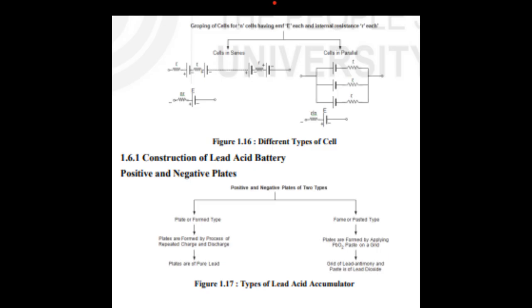1.4.2 Resistance of resistors in parallel. Resistors are said to be connected in parallel when the same voltage appears across each component with different current flows through each resistor. The total current flow into and out of the parallel combination is the sum of all the individual resistor currents, as shown in figure 1.6. Figure 1.6, Parallel resistance. Look at the screen. Two resistors connected in parallel may be used as a current divider. The voltage V appears across each resistor. Thus, we see that two parallel connected resistors function as a current divider.